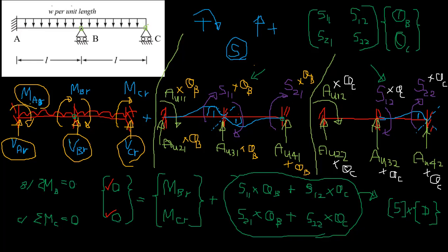So once you apply a load, the beam will rotate, right? So that means it cannot restrain it. So there will be no restraint force against the rotation. So that means no bending moment generated, right? There will be some bending moment in either side, but this point is a pin joint and the total bending moment is in equilibrium. It is equal and opposite, right?